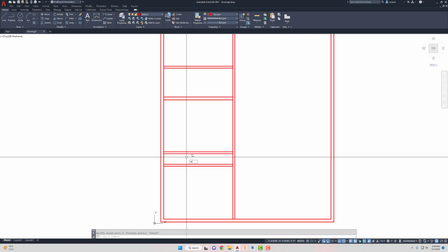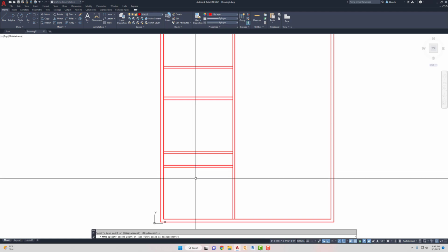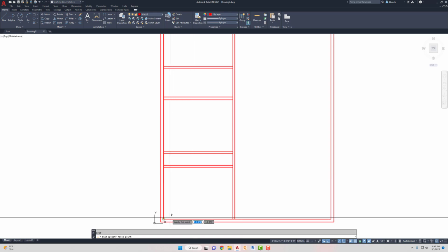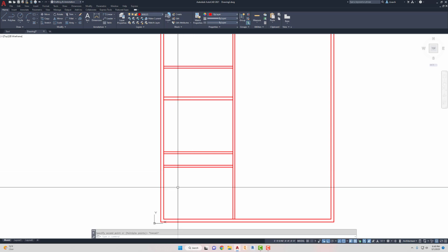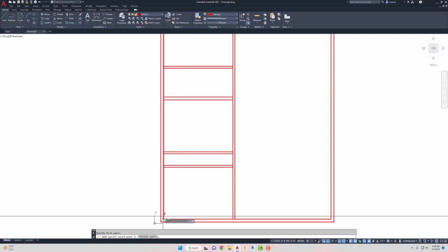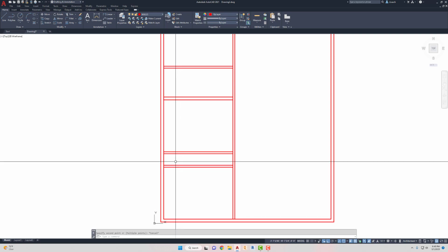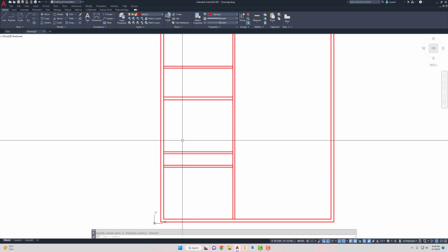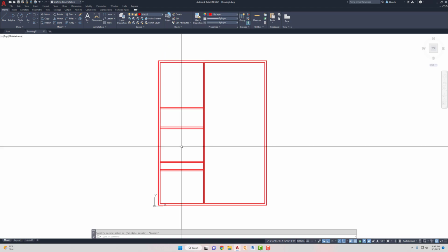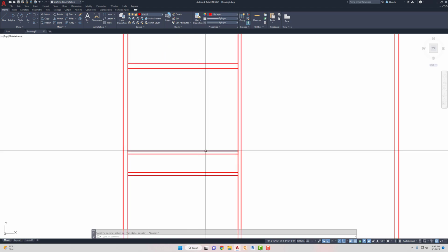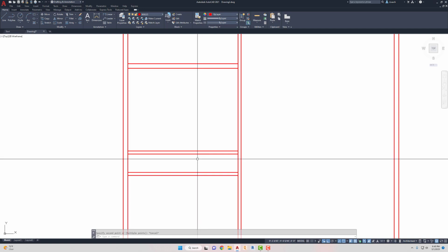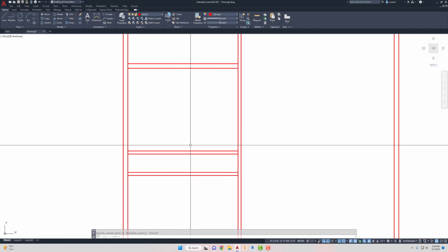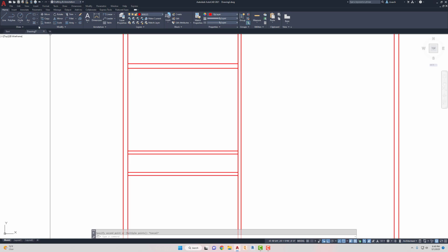And then I can move this. I'm gonna move this wall down 2 inches. Let's double check what I got here. I want to have 9 feet from here to here, which I do. Okay, and then in the closet, I want to have at least 24 inches, 2 feet. Yeah, that works. Okay, so there's those rows, and then this closet is kind of divided in half, so each room will get half a closet space.